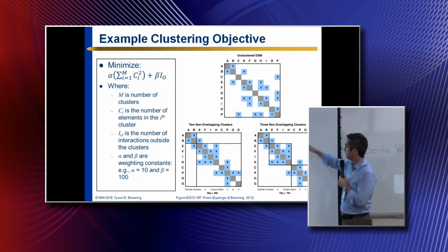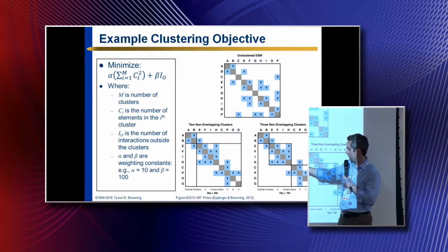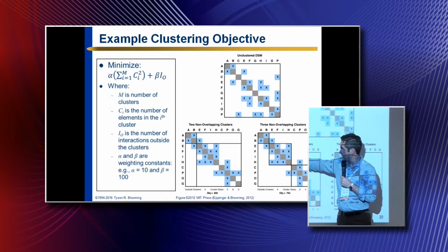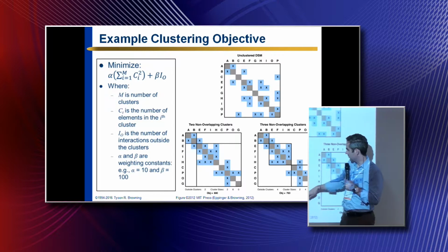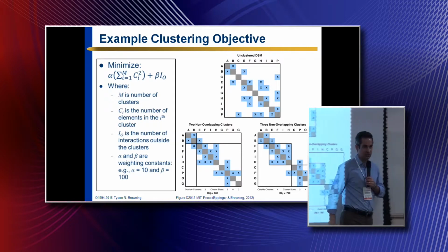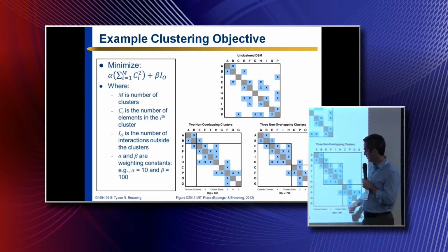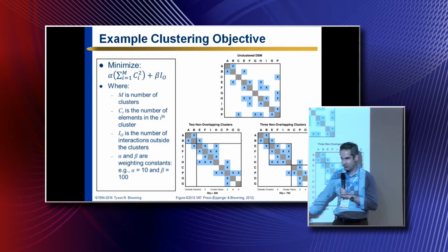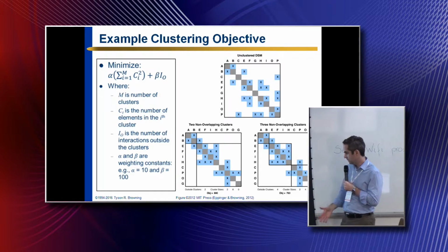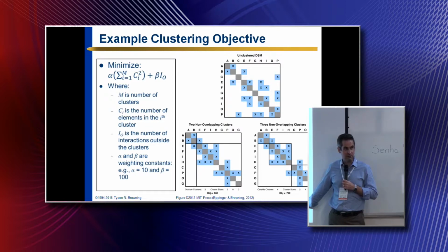So this compares an unclustered DSM example with a clustering result that has 2 non-overlapping clusters. Here's the first one. Here's the second one. You see it's one huge cluster and one small one, and 2 relationships outside of these cluster boundaries. And when you plug in this particular objective function, you get a number, 880. It's only meaningful in a relative sense. If you're trying to minimize, here's a number, 760, that's smaller, so it would be more optimal.